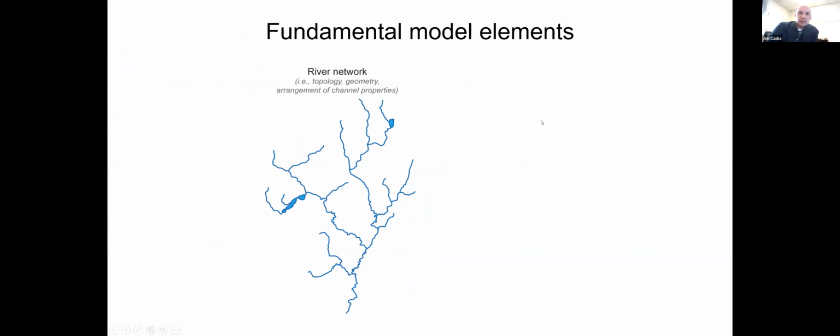And so the key fundamentals of this model, which I'll mostly talk about and then talk a little bit about applications toward the end, is that first and foremost, you need some sort of network, here a river network, and that network can include reservoirs or ponds or lakes. There's flexibility there in terms of what those links represent. But for this modeling, it's really coded to only thinking about fluvial transport. So we're really talking about river channels up to about 1, maybe 3% slope, where there's that handoff between the debris flow runout and fluvial transport specifically.